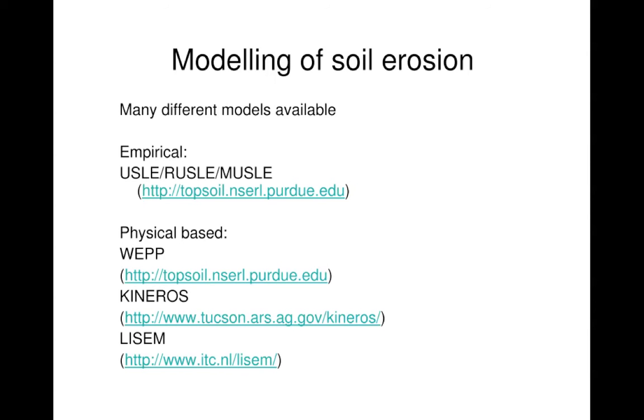developed in other soils. At the West Australian Soil Science Conference this year, and not surprising to me, but maybe to the guy who presented, he showed results where he used USLE empirical parameters to predict erosion at a mine site, and they didn't work. Didn't even come close to working at predicting the erodibility of materials. So USLE, I think, is useless, even though it seems to be a bit of an industry standard. That said, there are problems with physically based models as well, and we're going to talk about some of them.